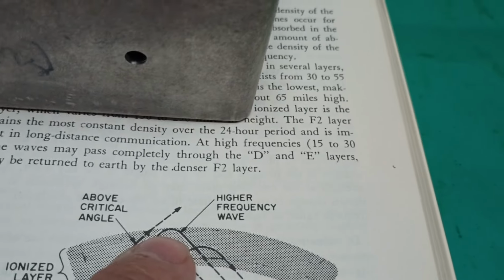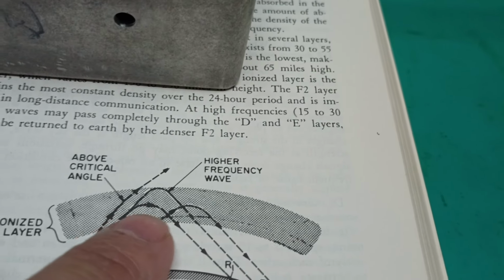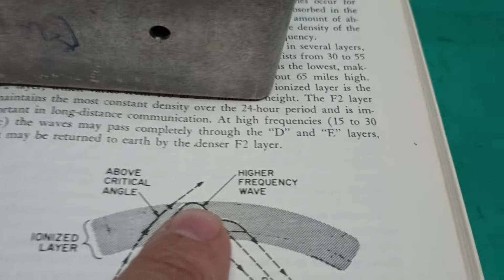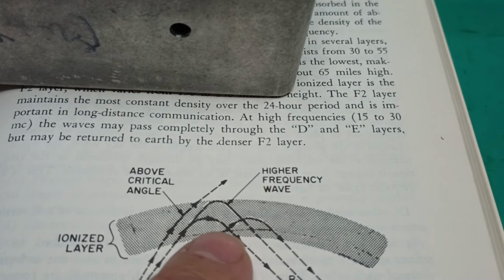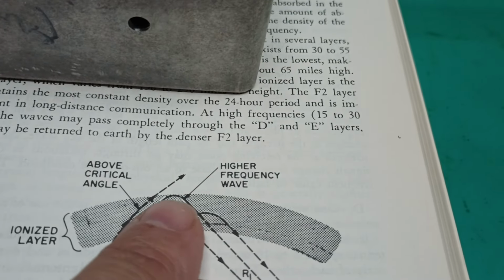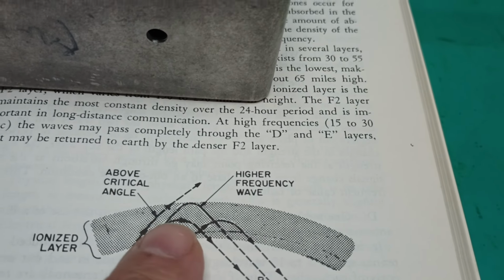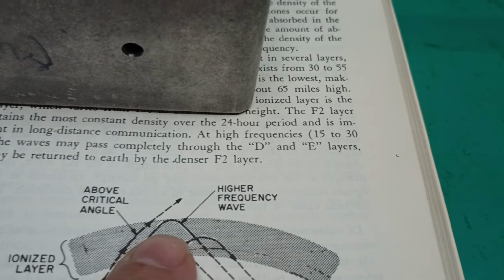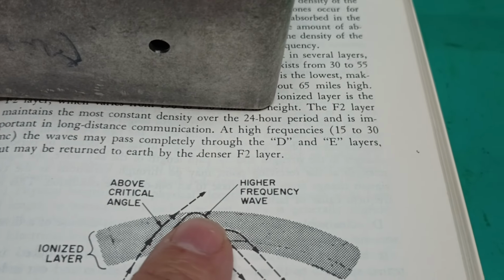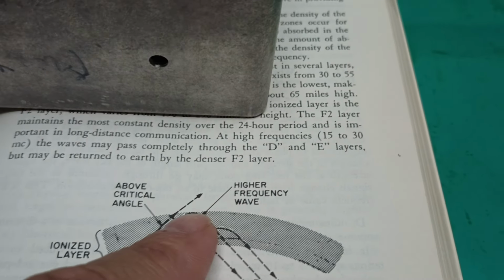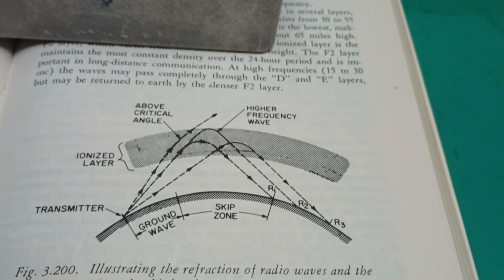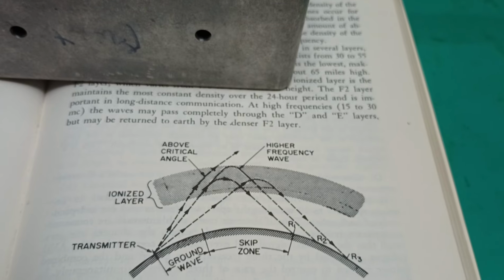Higher frequency wave. Here's where the myth of reflection from this mythical surface comes from. This higher frequency wave is doing the same thing as these two, but the reason they're showing it at the top of this, which could be falsely construed as reflecting off a surface, disagrees with these two because these two are not reflecting from any surface. So this one isn't either. The reason they're showing it there is to invoke this critical angle, which I've mentioned in my videos before. The higher frequency wave can only go up so high in this diagram before it, in my term, punches through and just keeps on going into outer space. So this exposes this myth of reflecting off this non-existent layer up there.